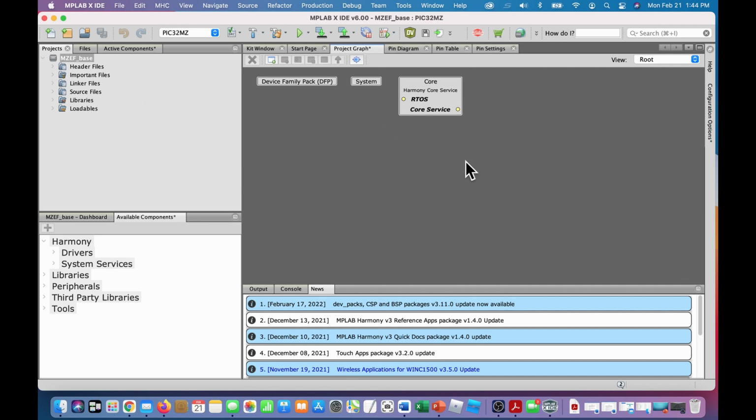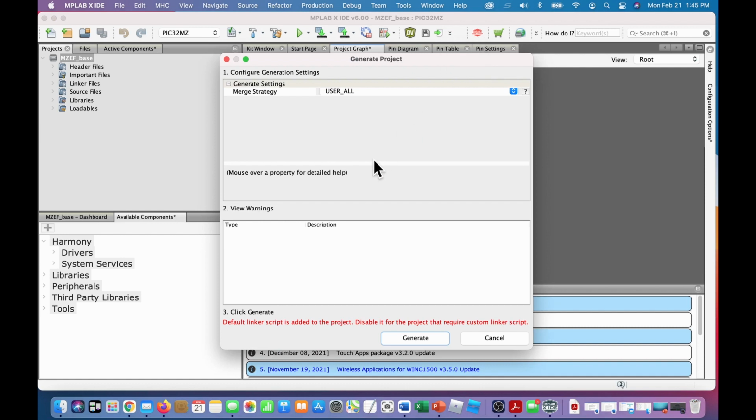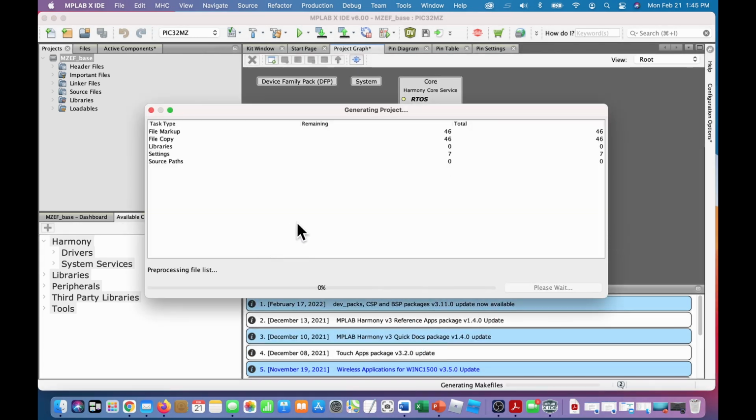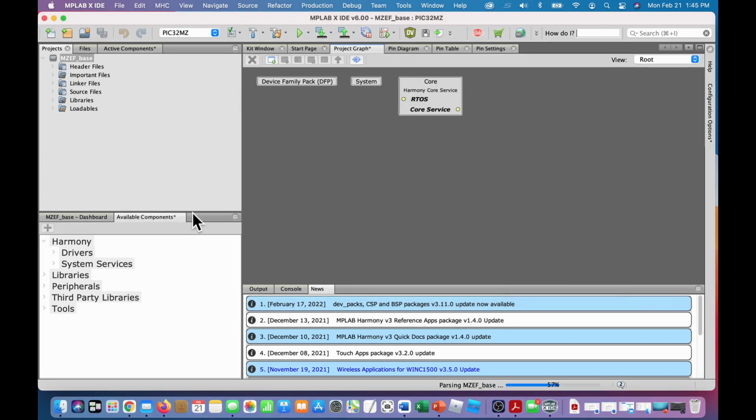all these settings. And there's, again, two ways to do this. MHC, generate code there. Okay, so you got to find that. The easier way is to look over here to this little icon, the code icon. Click on that. And we just say generate. And so it's generating all sorts of stuff based on our configuration. Great.